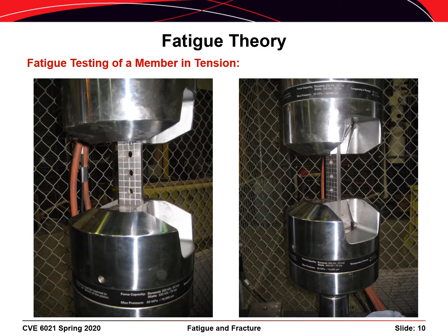It isn't very practical to test full bridges in a laboratory like the car two slides ago, but we can take components, called fatigue details, into our labs, and we can subject those to cyclic loads to simulate what they might be subjected to in a field environment. This slide shows a piece of bar stock with holes drilled in it or cut into it, and it was subjected to a cyclic fatigue type of loading until failure was observed.